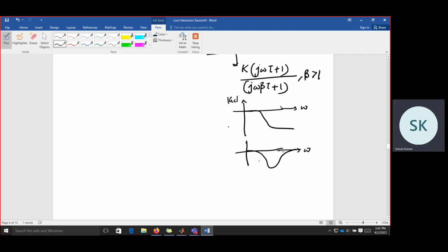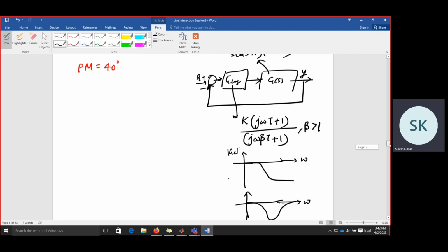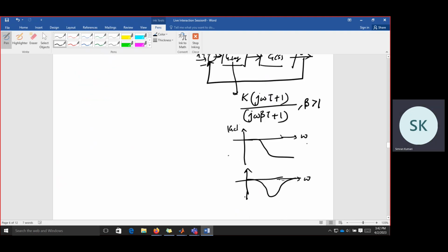So this phase shift is a negative phase shift. So basically it causes a slower response of the compensated system. And here we can see this 0 dB line. So it passes the lower frequencies without changing them, but with increasing frequency, attenuation increases.